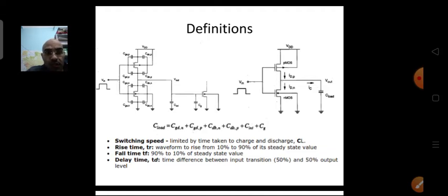Okay, so you see the switching speed of the device or any circuit will depend upon your load capacitance, or the combination of all these capacitances. So that is important. That is why we have to minimize this capacitance as much as possible. Then we cannot increase it too much. Although there are some advantages of increasing the capacitance, the delay will increase because of this. And you will see later on that the power dissipation will also increase, so we'll try to minimize that.